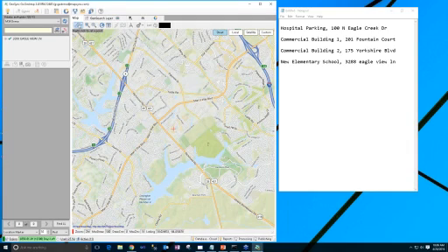So now let's check on our layer. Our workflow layer that we're going to use is our GS construction site. I'm going to open that layer up, and we said that it's critical that that layer has to be a workflow layer. So when we open that up, one way I know immediately whether this is a workflow layer is when this opens up, this timer will start running. So the workflow layer actually gets a snapshot of data from our workflow database, and then it sits there and it lets us know how long it's been since we refreshed that layer. But if this timer is running, we know that that's a workflow layer.